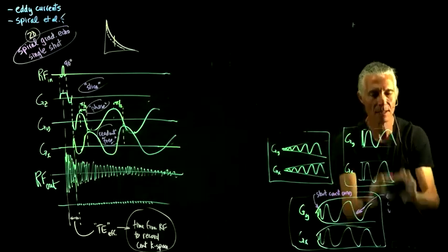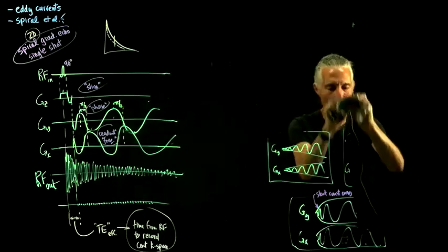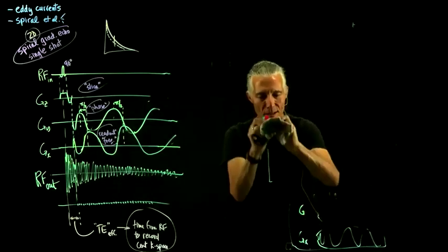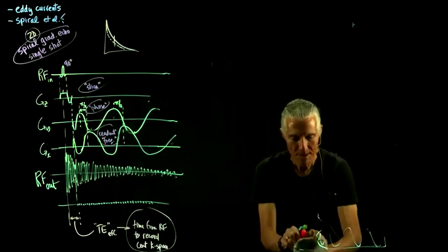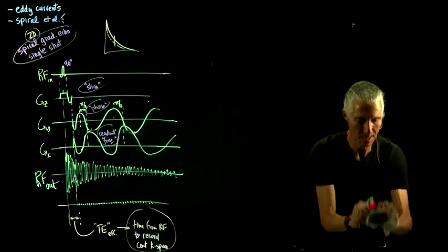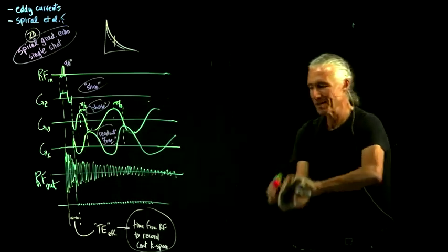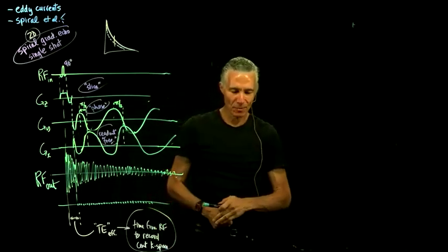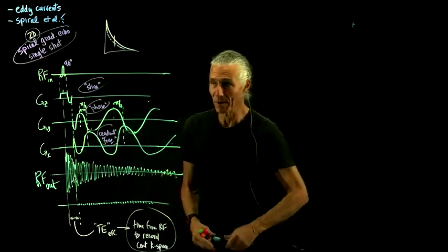So, going from the center out. Now, one thing there is that if you do that, you'll record the center of k-space multiple times. So in some ways, you could argue it's a little wasteful to record it so many times, although there's several reasons why you might want to do that.